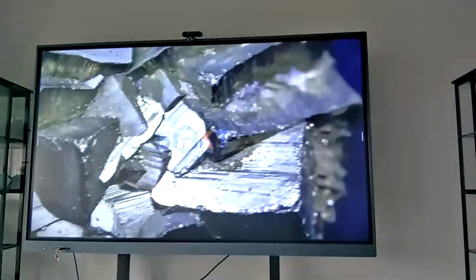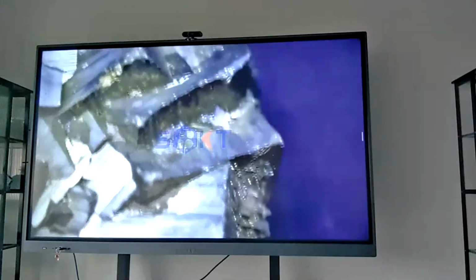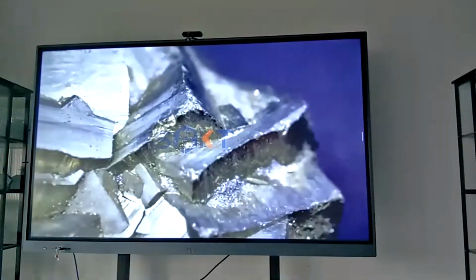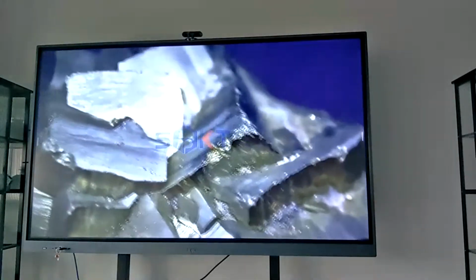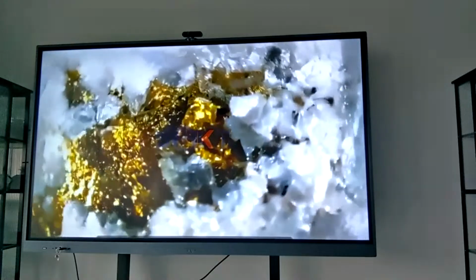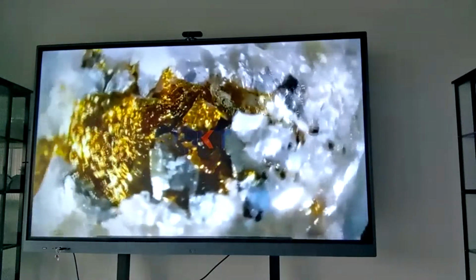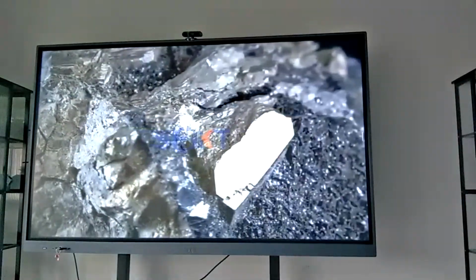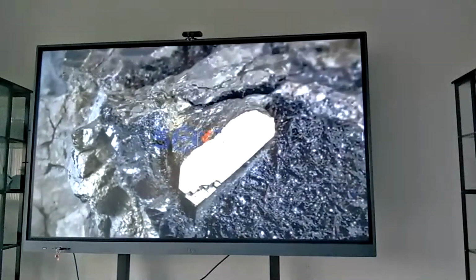Granulation with cement or other binders is necessary to solidify the fine mud. Otherwise, heap leaching will fail, causing channeling and even penetration problems.